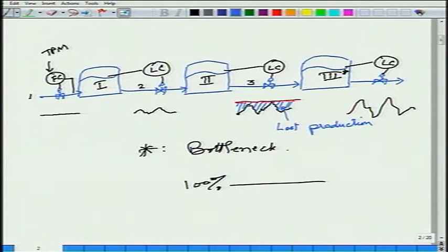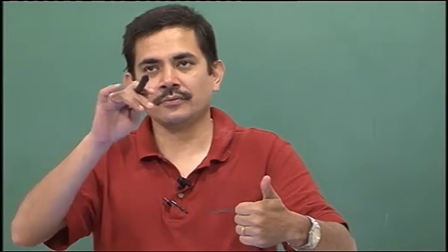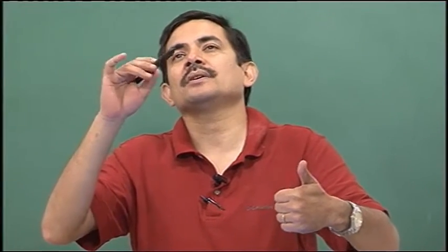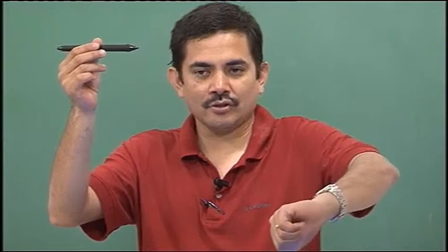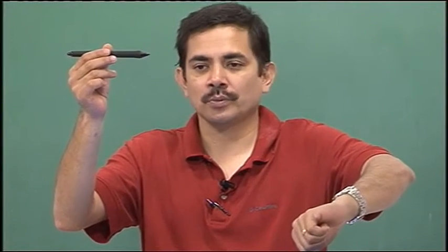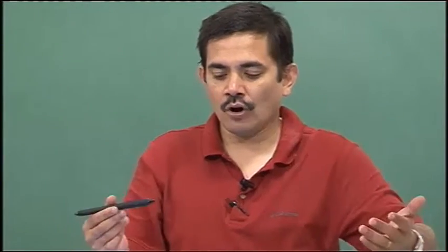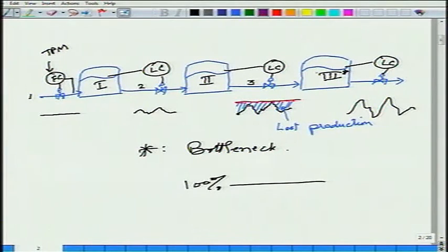All right. If you want to automate this, right now what is the operator doing? The operator is looking at unit 3, which is the bottleneck unit, seeing the feed to that bottleneck unit, and if he sees that yes, I have approached my maximum constraint closely enough, he stops adjusting, he stops increasing the throughput manipulator, right? I can automate this by saying that look, I am looking at my constraint variable, maybe I will take whatever is my constraint variable, I will call it active constraint controller. Okay. The job that the operator is doing, a controller can also do.